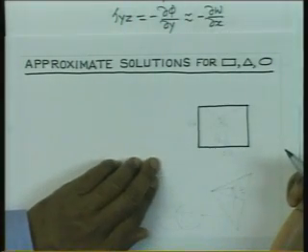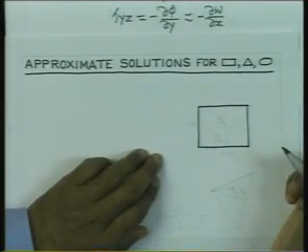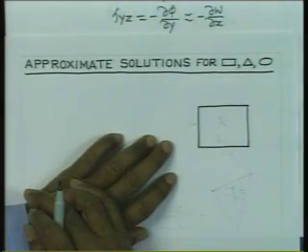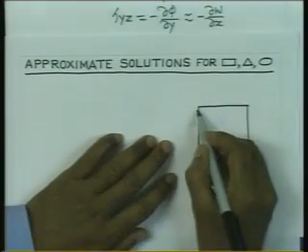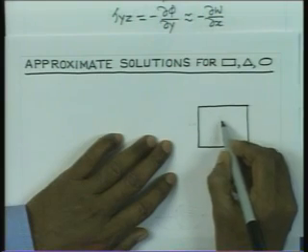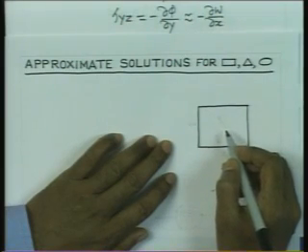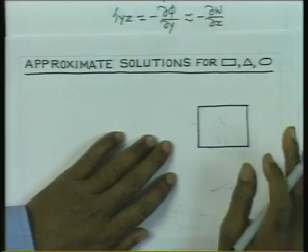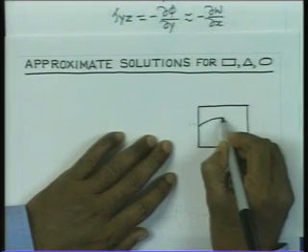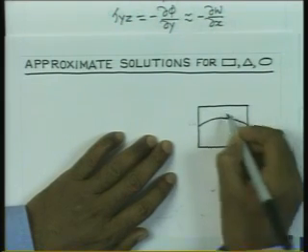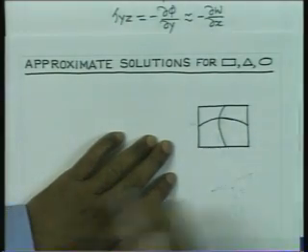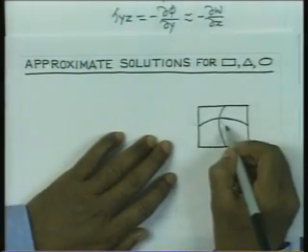let us say this is the section. So, therefore, the membrane is going to have this boundary, and if we now imagine the membrane to deflect, obviously the membrane is going to have 0 deflection along the boundary, and it is going to have maximum deflection at the center, and that shape you can imagine is a doubly curved surface. So, we can imagine that this is the shape of the surface, and we certainly have the maximum deflection at the center.